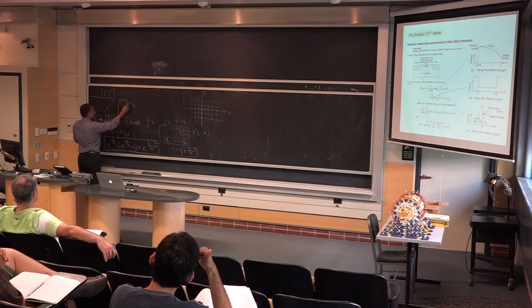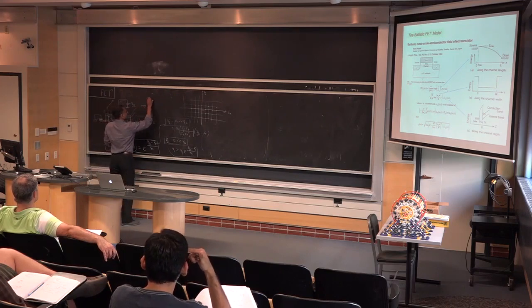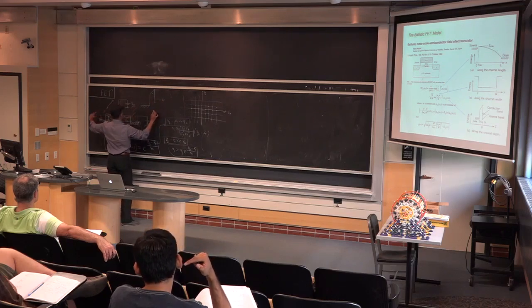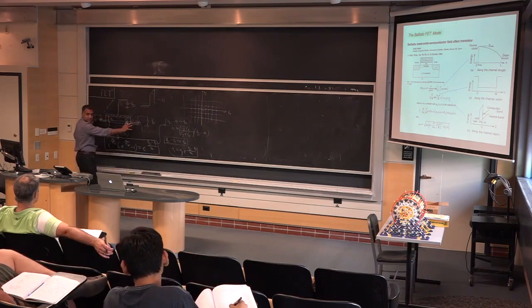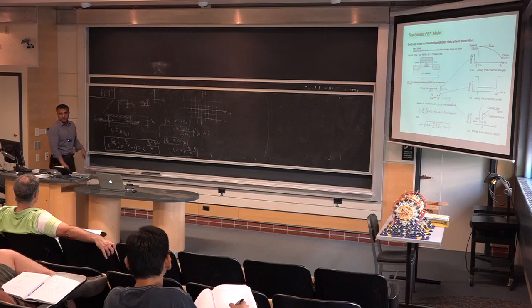Remember when you apply the gate voltage, again in terms of the band diagram, this is what happened. The Fermi level you can consider of the source or the drain. When they're shorted, they're the same, right? Source and the drain are the same. And the conduction band of the semiconductor is here, and the Fermi level of the metal is here, and this is your Q times VGS. We drew this picture, and then you fill it.